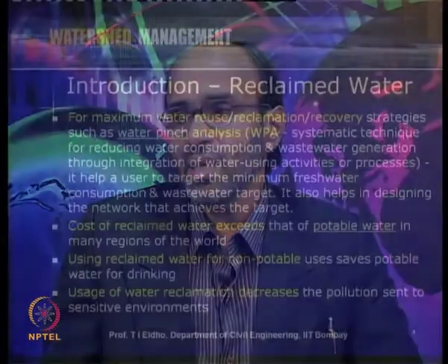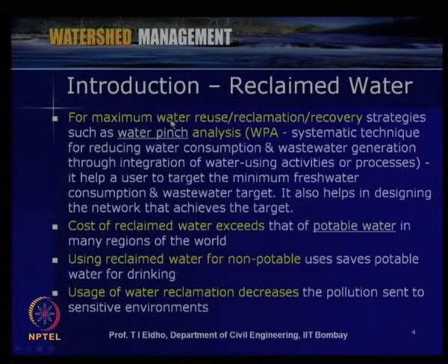Now, for maximum water use, reclamation or recovery, we have to select appropriate strategies, such as water pinch analysis. Water pinch analysis is an analysis which is done in many countries. It is a systematic technique for reducing water consumption and wastewater generation through integration of water using activities or processes.